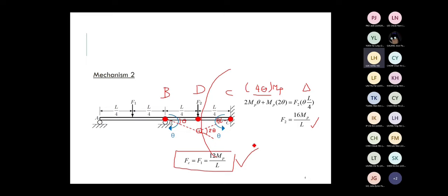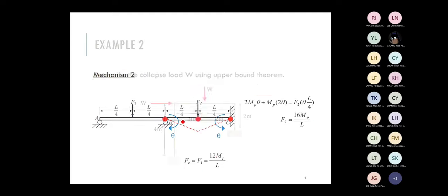Okay, continuous beam. The trick of doing a continuous beam is to consider failure on each span separately. Relatively easy. If you're familiar with the method, I believe that each mechanism only takes you around 1 minute for your calculations. So it's relatively straightforward for this part.